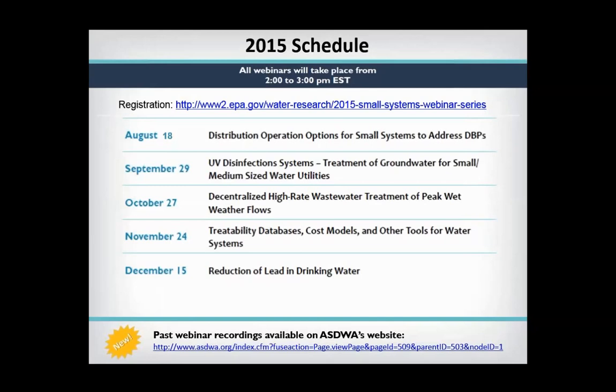One of the other things that can happen is that, hydraulically, sometimes these things have a huge adverse impact on C factors as well. And they deposit on the pipes. So it's a bit of a double-edged sword, because it can render the orthophosphate not highly reactive in the way you intended, but it can put a diffusion barrier on the pipe. So the only way to find out whether it's good or bad is really sampling sites, doing profile sampling, and finding out if water contacting these deposits has high lead levels or not. So those are the real impacts of the alum carryover.